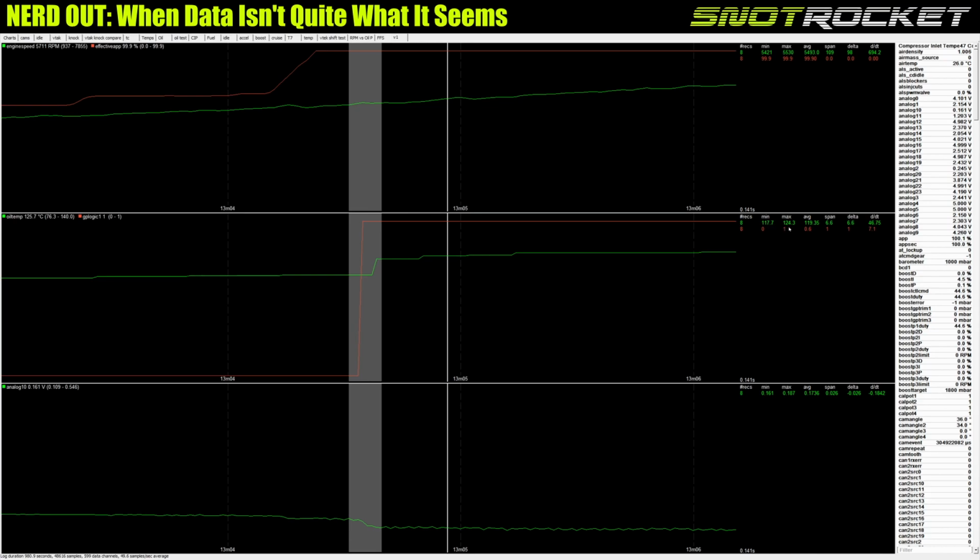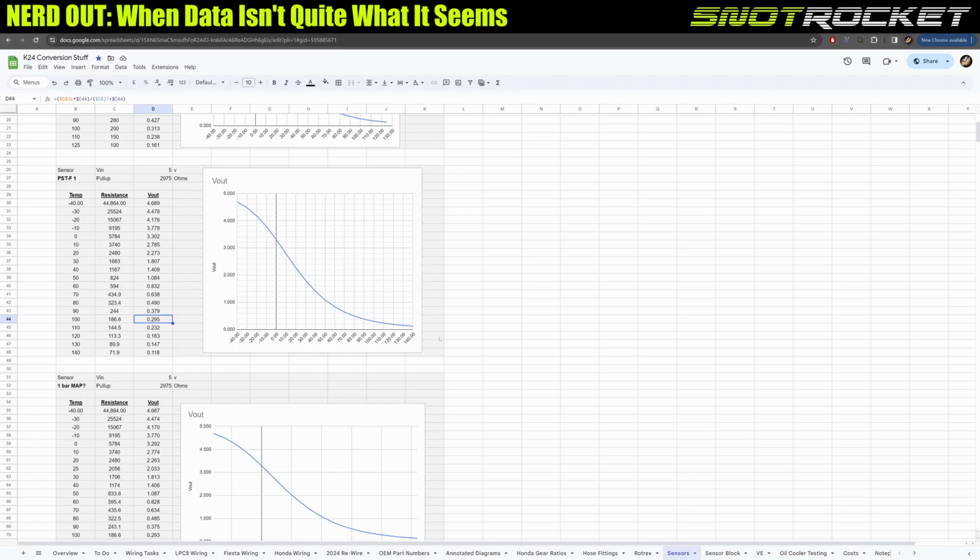So it's a 7-degree shift for a 0.026 change in voltage. So what that means is the resolution at this part of the chart here, the way the sensor's been linearized, is there's pretty much zero noise immunity. Like a 0.02 volt shift is resulting in 7 or 10 degrees change in the perceived temperature rating or output of the sensor. And that's not good, right? So we need to fix that.